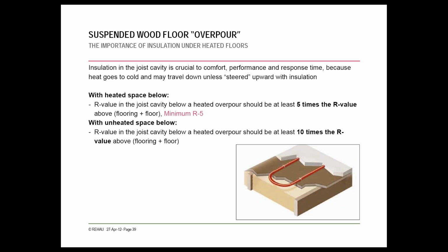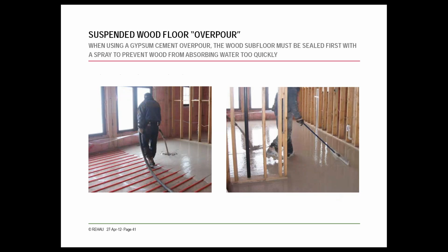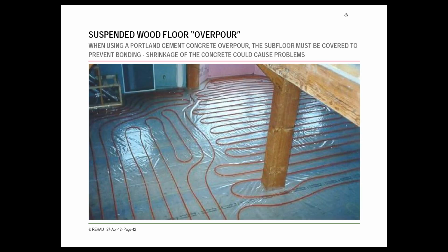I did get another question about using bend supports, and I will touch on those, but where the tubing is coming in and out of the slab and going up to the manifold, that is definitely something that you want to utilize. Here they are just topping off the slab with the wet gypsum concrete.